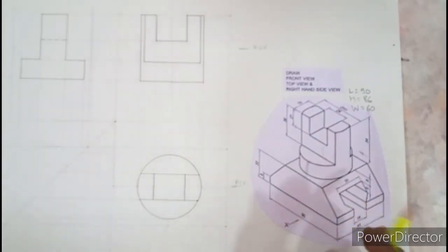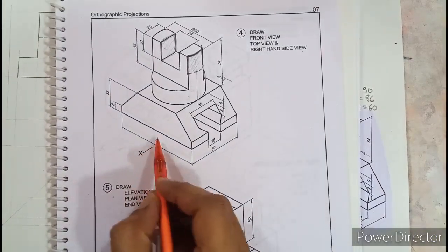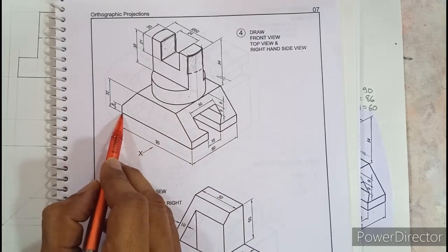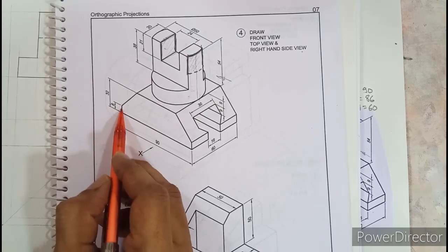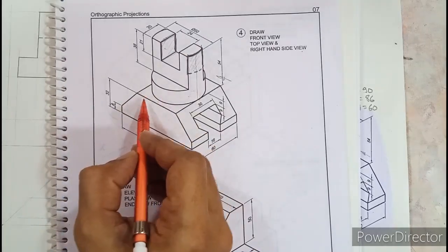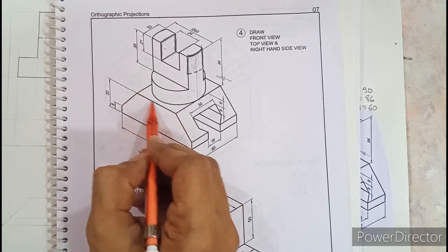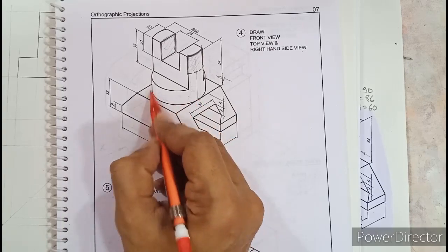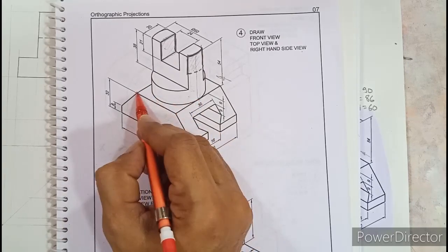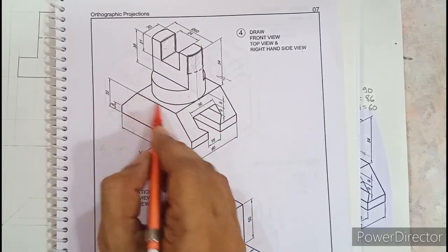Okay, so starting from the front view, let us draw the platform now. This platform is 90 millimeter length, 8 mm is the height up till here, and then the inclined surface. You can see that this length is not given, but it purely measures with the diameter of the cylinder. If you look at this cylinder diameter, it is in line with this diameter, that is 50. So this diameter is 50, and even this length is 50. Okay, so this length is 98 millimeter and the above one is 50.